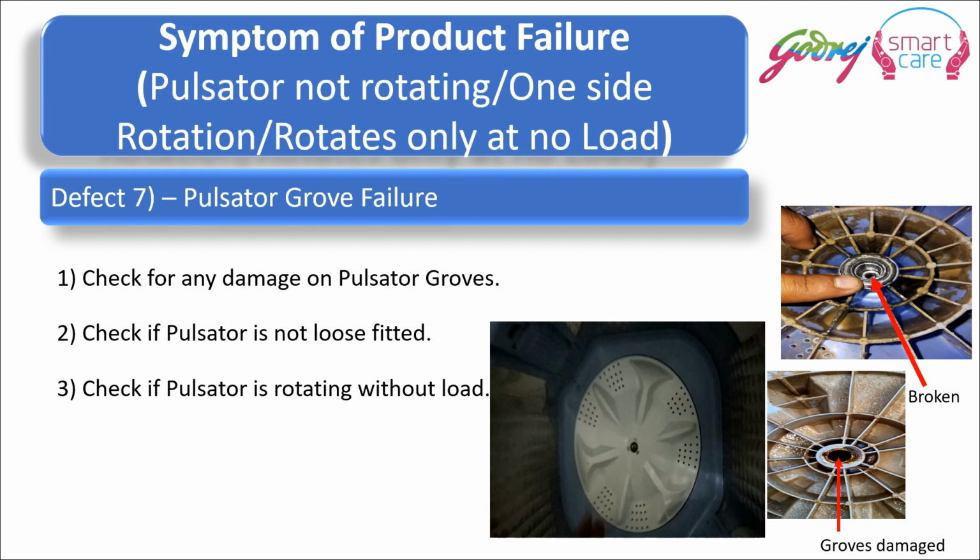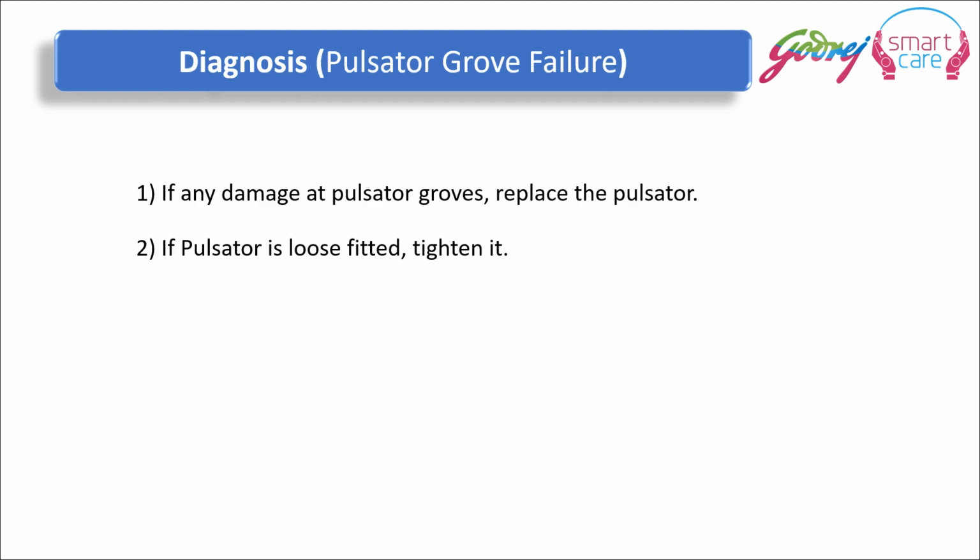Pulsator grooves failure. In that case, we have to check for any damage in the pulsator grooves. If the pulsator is not loosely fitted, we have to check if the pulsator is rotating without load. If there is any damage to the pulsator grooves, we have to replace the pulsator. If the pulsator is loosely fitted, we have to tighten it.